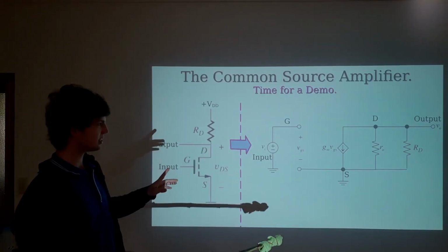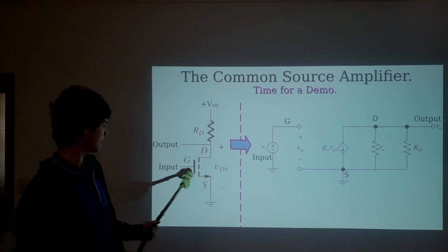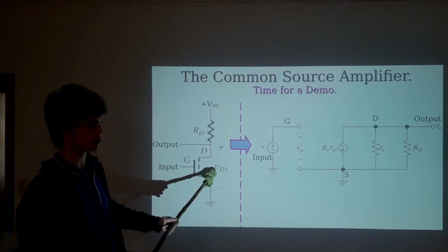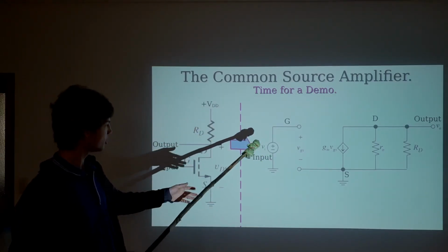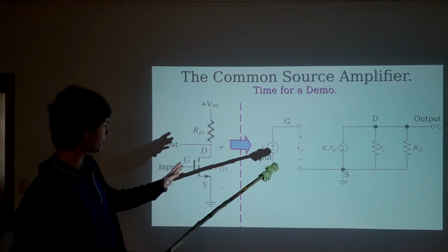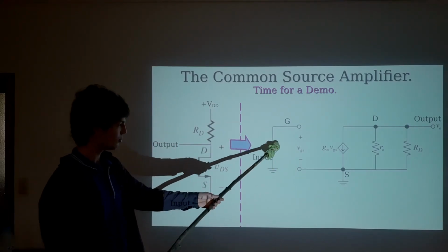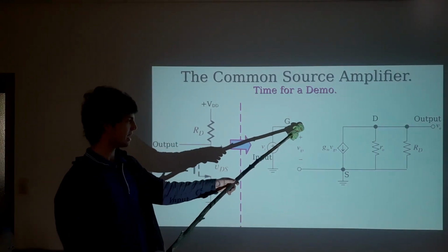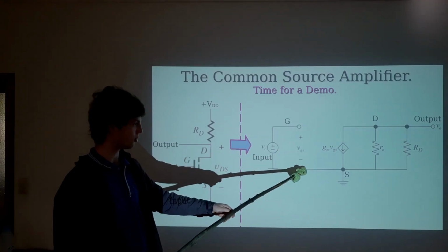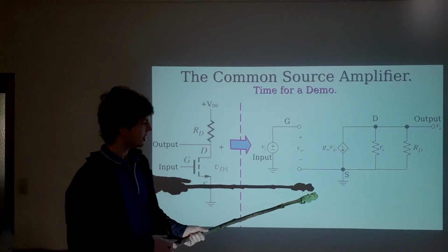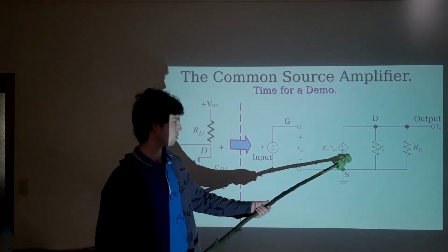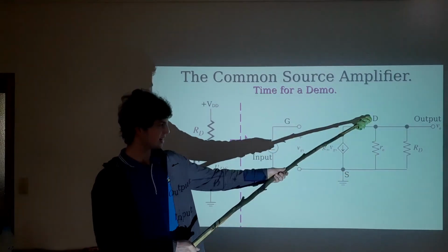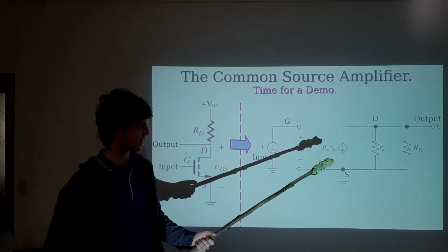Now, this is an interesting point here. We've got this whole system. We have our input here, and we've figured out that it's going to have an amplified output here because of the squared dependence on current through this bit, the resistor, Ohm's law, and so forth. So let's break that apart a bit. We have our input here, which is oscillating. It's a really small input, and that goes to our gate. Then we have essentially a capacitance over here, a voltage between the gate and the source. Now, we've already seen this part before. We've seen this modelling the current that's going from the drain to the source through that channel region. We've just explained this little resistor here that we throw in for the channel length modulation.